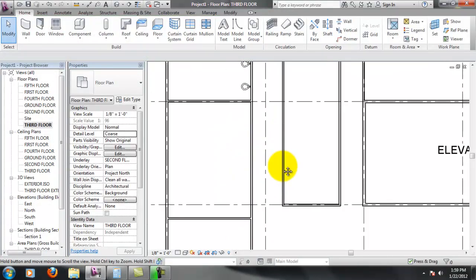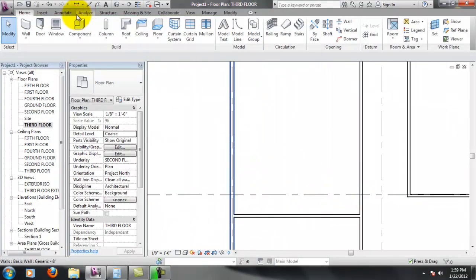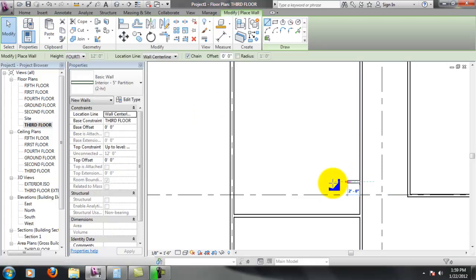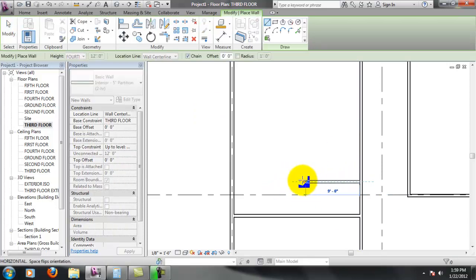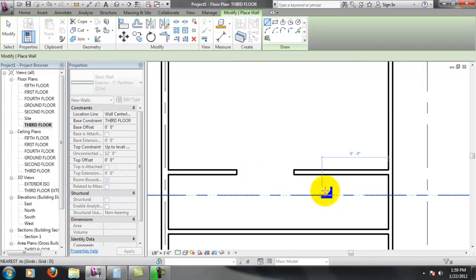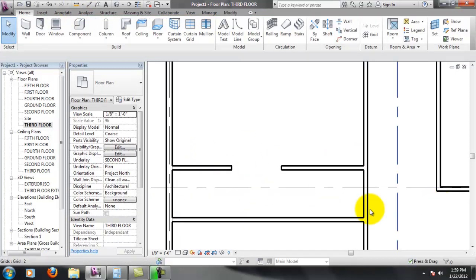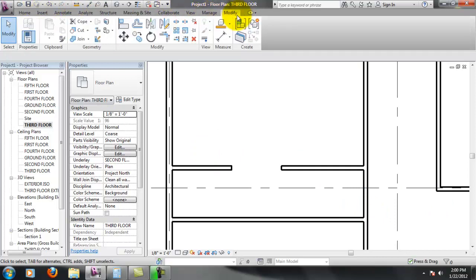I am going to go ahead and drop this other wall in here and add the door. So I'll hit that wall there. I'm going to use my extension this time. Notice that blue dashed line comes over here, which tells me now these are in line. It's okay to go ahead and align these though. That way they're locked together. I'll use modify, align again, and lock that. That way when I move one, it moves the other one.